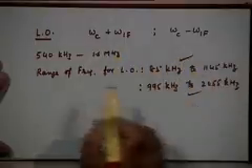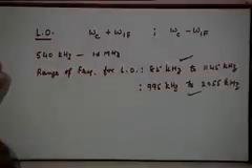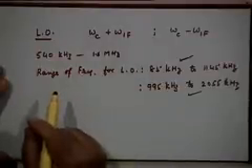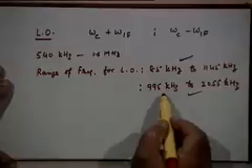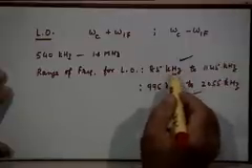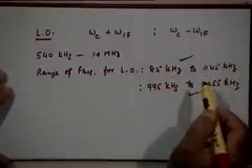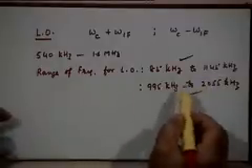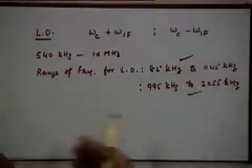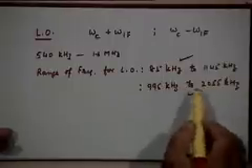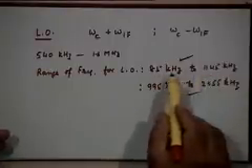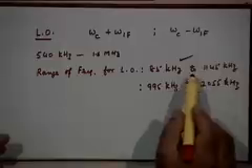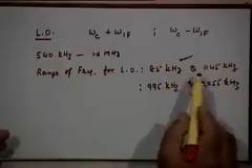So the issue of whether to choose this or this really boils down to which is better to use, or which is easier to build. What is your gut feeling about it? The upper one or the lower one? Which oscillator do you think will be easier to design? Lower one. Why? The ratio of the frequencies that you need to vary it over. You want a tunable, variable frequency oscillator, and the ratio of frequency is almost just 1:2 here, whereas here it is 1:20 almost, not 20, about 13-14.